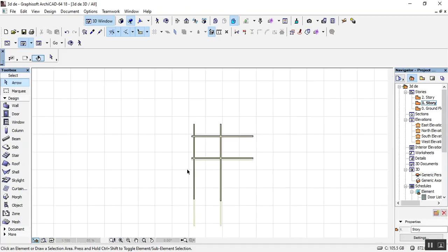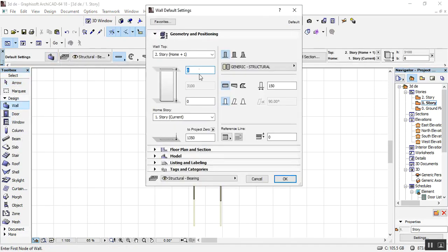In a situation whereby you want a beam here, let's assume you want a beam here and you want to create a wall with a beam. So you just come down to this wall, you come to these settings, you change it to 450 millimeter, you come down to this bottom offset to zero. This means you want the block to go from the ground level to a certain height, like you want to create a beam. So the normal height of a beam here is 2650. That's the normal height we use here, 2650. Then if you have 2650 and this is 0, you can see that the total here is 450. This is the bottom. You can see the space.